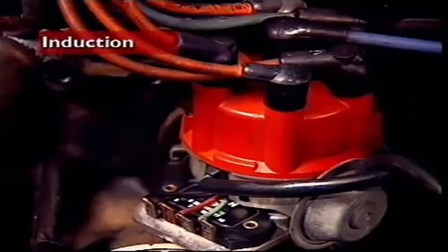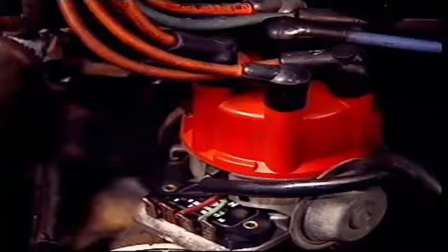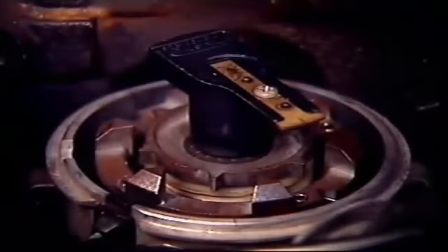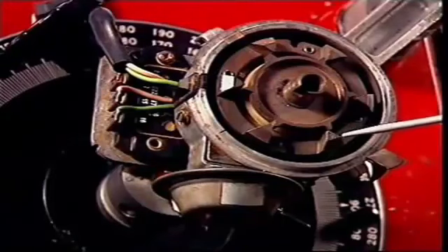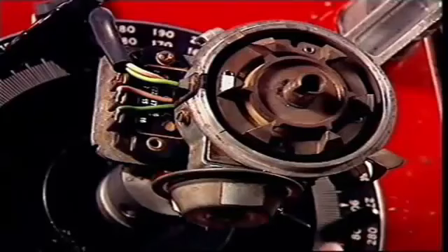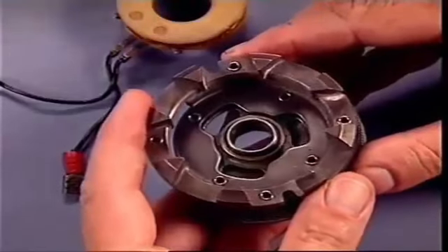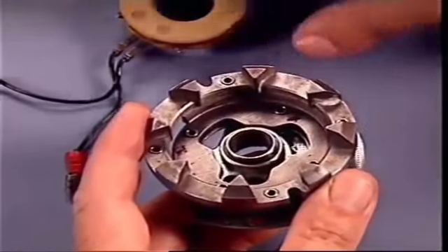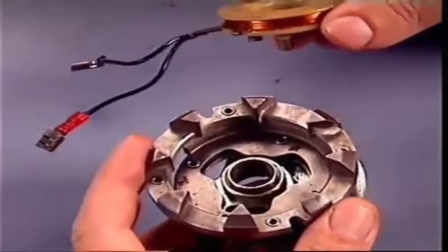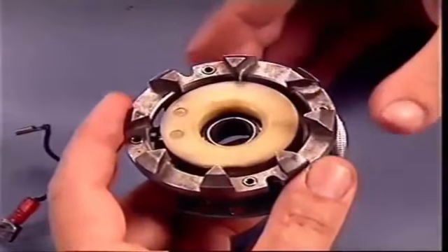In electronic ignition systems, the contact breaker is eliminated and the switching or triggering of the primary circuit is carried out electronically. In induction-type systems, a pulse generator has a stator mounted on the distributor body and a rotor unit called a reluctor attached to the distributor shaft. The stator has a circular permanent magnet with a number of projections or teeth corresponding to the number of engine cylinders, and a stationary coil of fine enamelled copper wire wound on a plastic reel and positioned inside the magnet.